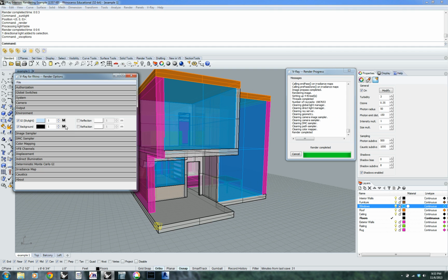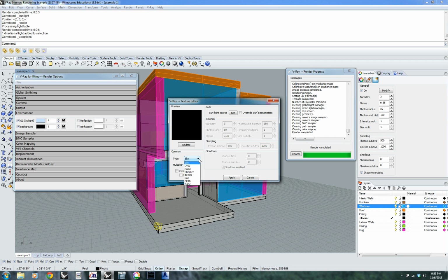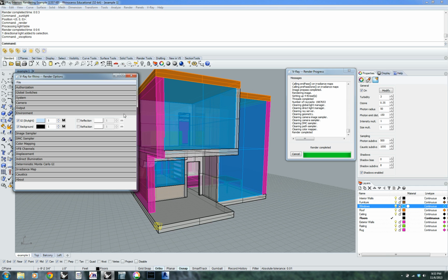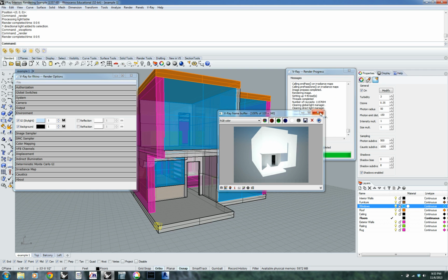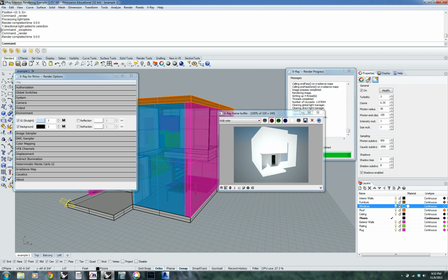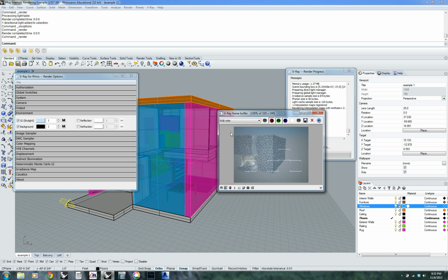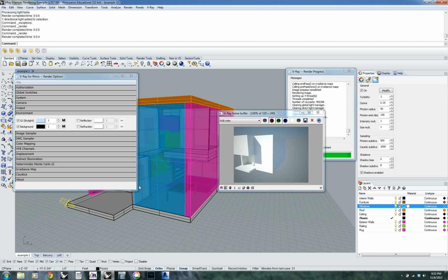So as you can see, I'll just go right back into that. Right now our lighting system is set to sky, and that's how we want it. It's going to apply a pretty good natural daylight system, and now you'll see that the sun is coming solely from our one source of sunlight, and those shadows are always going to come from the same direction, exactly where we want them to be. So even if I rotate around, instead of it coming from right over our shoulder, which is the default sunlight system, now it's going to come from this direction.